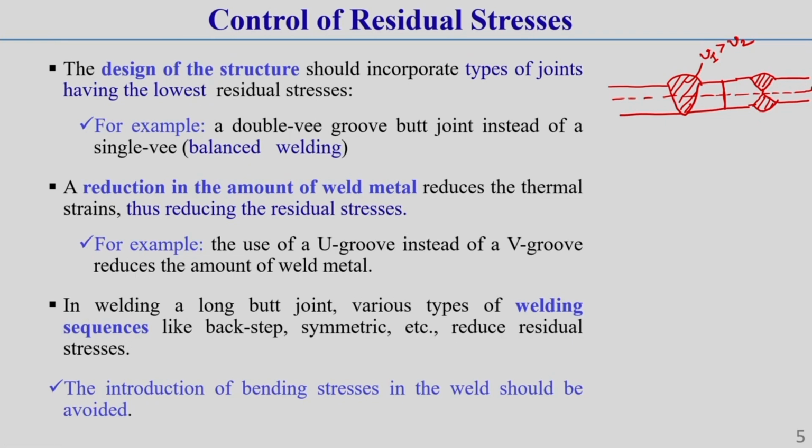So, due to this volume of molten material related issue, in single V there will be more sinkage type of force, or you can say thermal expansion as well as contraction type of force, in this weld zone. So, during cooling as more contraction force will be developed, in this single V bar joint the residual stress distribution will be more, as here the volume of material in double V is less. Now about this neutral axis, neutral axis means through the thickness at the middle zone.